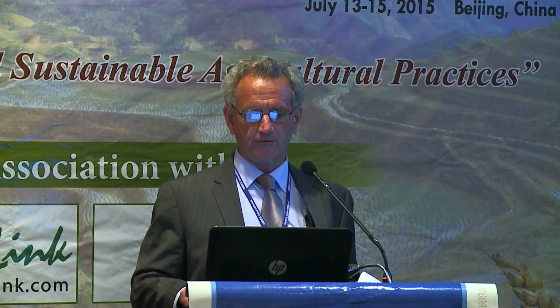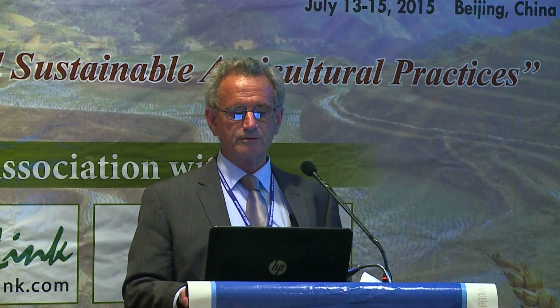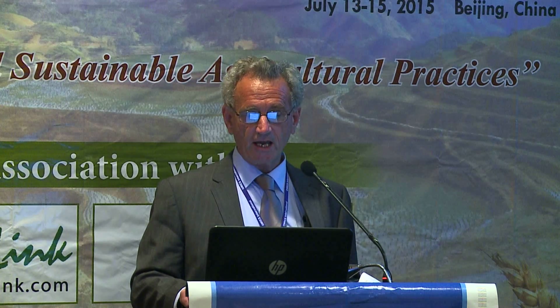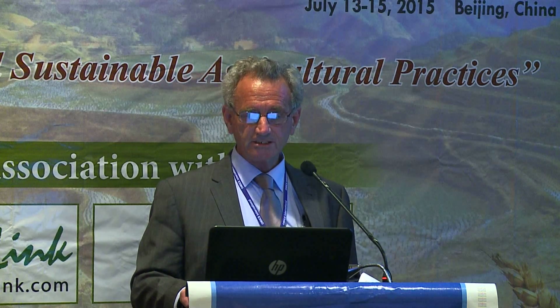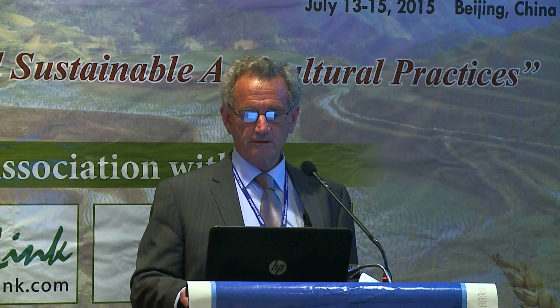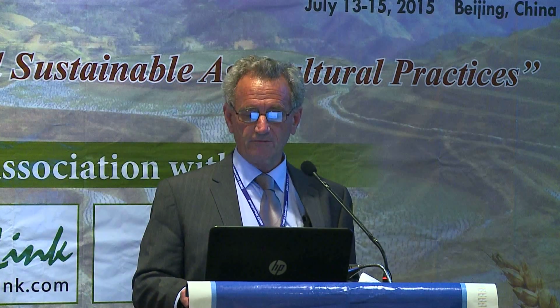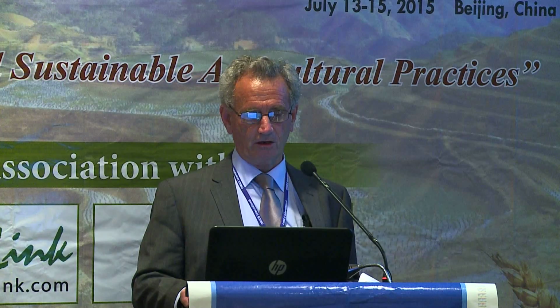4, you can adjust the irrigation frequency by adjusting the water level at which the irrigation starts. For example, if you require more frequent irrigation with less water, then start the irrigation when the water level is less than 1 centimetre below the level line. And on the other hand, if you require less frequent irrigation with more water, then start the irrigation when the water level is more than 1 centimetre below the level line.